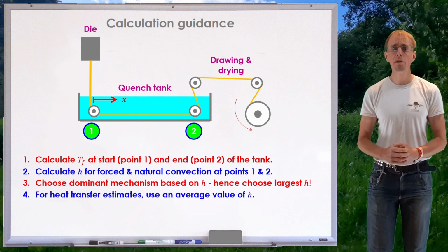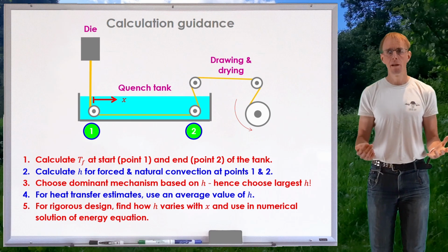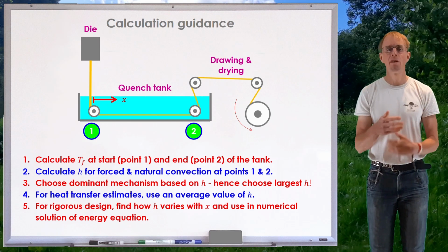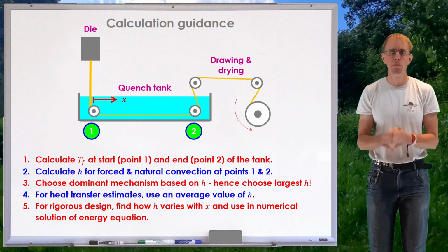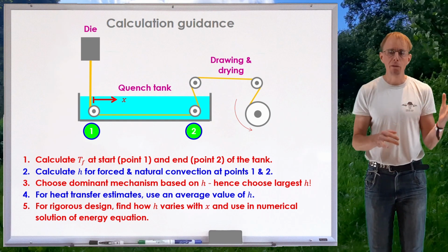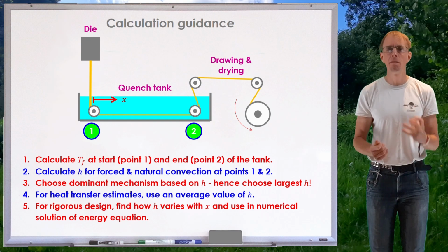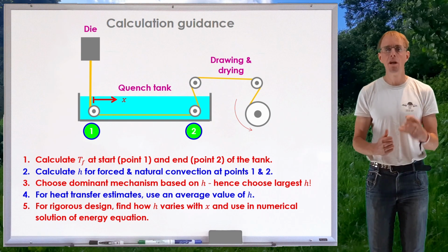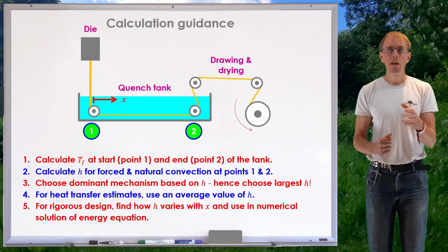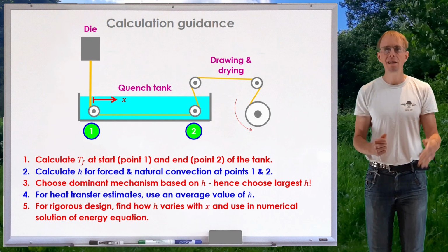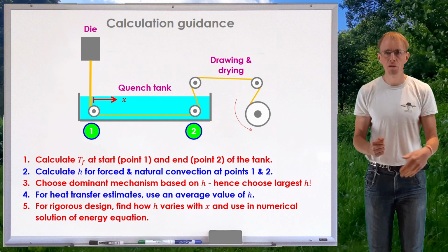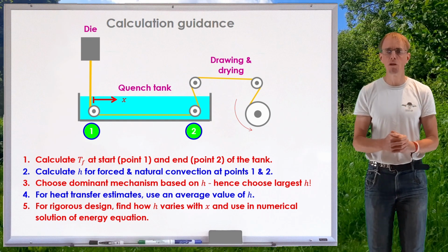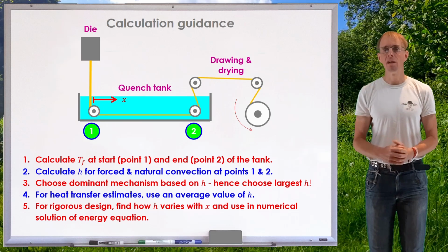Of course, another way we could do this is entirely numerically. And if we're constructing a numerical solution, we can build in the temperature variation of the physical properties as part of the problem that we're solving, and solve what is actually quite a complex coupled set of differential equations right at the get-go, such that h is always depending on T, T is depending on x, T is also depending on the value of h, and so we've got this coupled set of equations that we can solve where we don't actually have to manually iterate to a solution.